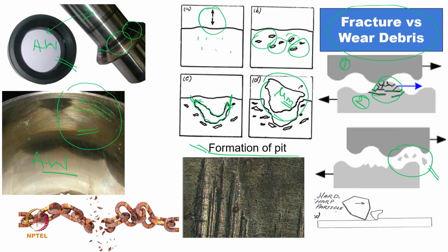So, this again is a kind of fracture, and this fracture can be utilized for this purpose. Now, if I try to figure out the morphology of these particles, I can judge what kind of load condition is happening inside the surface, how many particles are coming, and what the chemical composition of this debris is. I will get complete information.